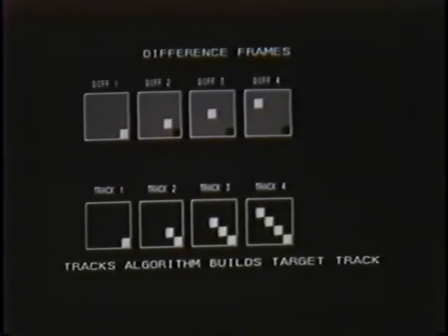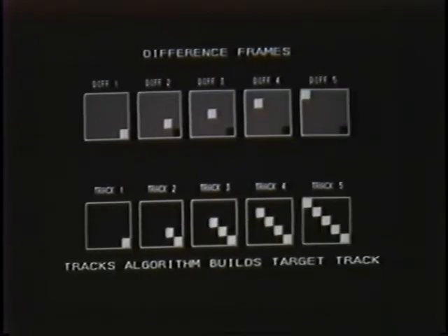Because the final TRACS image consists of only two different intensities, black and white, a computer can now easily identify the target track. In cases where enhancement was insufficient, and as a result, clutter leakage is extreme, the TRACS algorithm may be misled to follow false tracks.